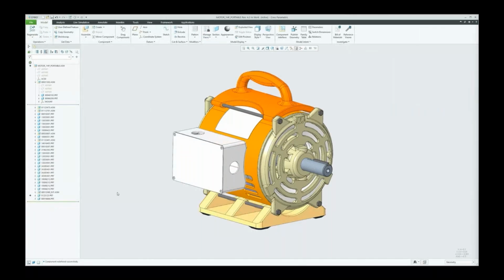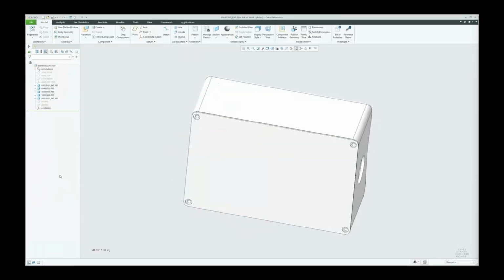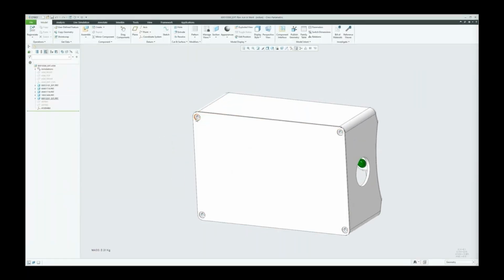There is just one aspect that we need to finish off though, which is on this electrical housing. And this is an opportunity to show off some part classification and how a design engineer might leverage this. So we need some bolts, but maybe Dennis can't remember the part numbers of the bolts that are required for this housing. So we're going to use part classification to help us find what it is we require from within Windchill.